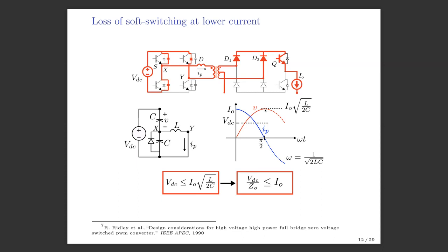So now what will happen is that this voltage will start rising, right? And the moment this voltage reaches the DC bus voltage, the voltage across this capacitor will become zero because the sum of these two voltages is zero, right? So if that happens, then what will happen? This diode will get forward biased now, right? And this process will stop at this point.